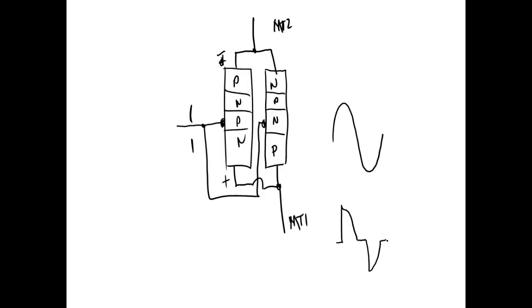So my average, my RMS value has got to go down, right? You understand? And this is where a true RMS meter would work. Your regular meter uses the peak voltage over pi. I'm sorry, of course, no, it doesn't use that. What your meter uses is that 0.707. That's only for a sine wave, right? You understand that? Well, the problem is this is not a sine wave anymore.